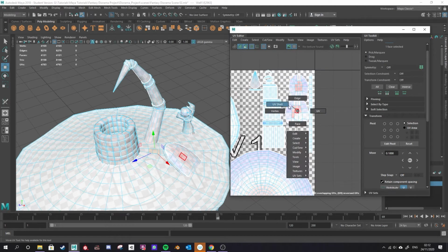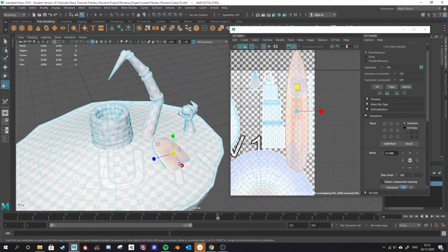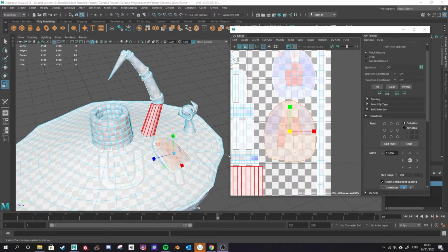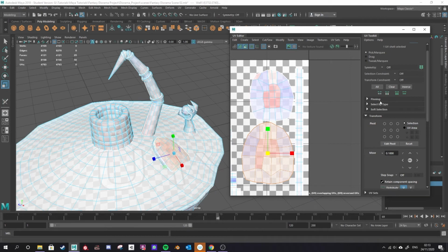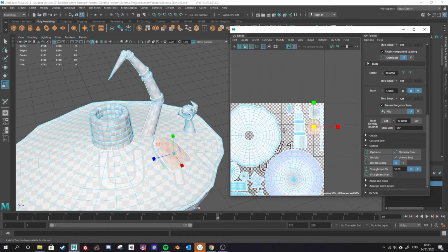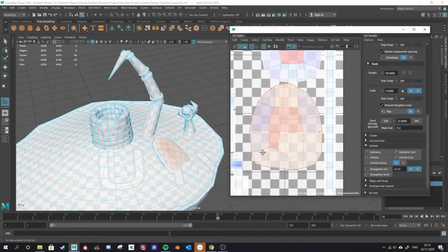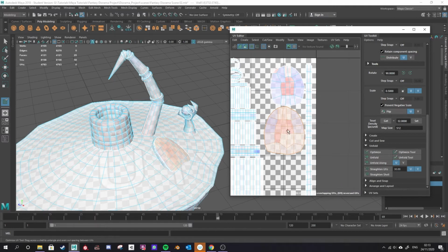If I was to grab an object shell and properly stretch it, you would see that it highlights most of it in red. Now, if these errors look really bad to you, you could go in with some of the tools in your UV toolkit to fix them. The Optimise and Unfold tools will be handy. Again, you press B and middle mouse to drag the brush size bigger or smaller, and you can use those tools to help re-optimize the shapes so that they may work a little better.